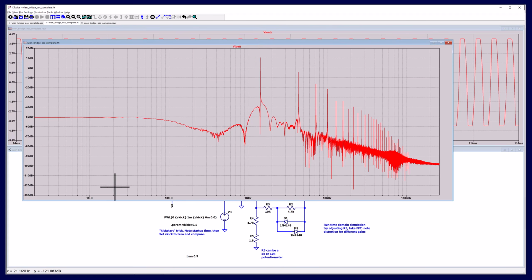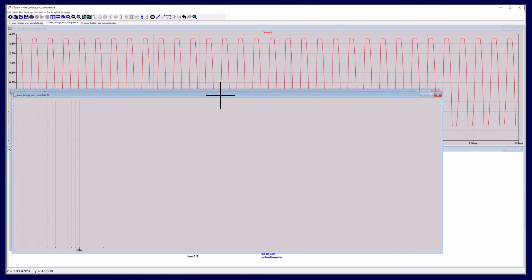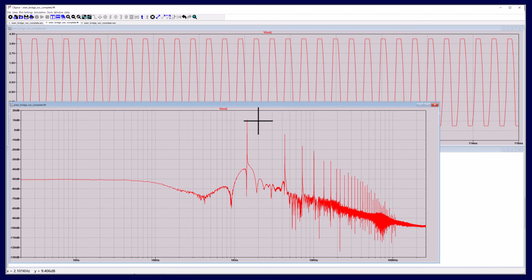And if I look down in the lower left-hand corner, let's move this down so we can see a little bit better. This is about, yeah, so it's about 1.5 kilohertz. And then at 4.4 kilohertz, so this is the third harmonic, I get a tone, the fifth harmonic, and so on. And if we want to quantify that, I can measure the difference between the two. Wow, that's only 15 dB distortion, right? So that's not a very good sine wave.